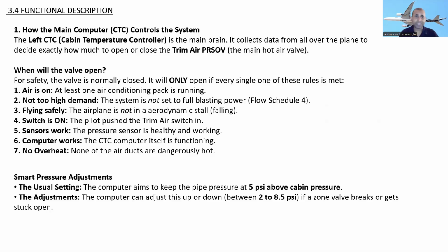Right. For safety, the valve is normally closed. The trim air regulating valves are normally closed for safety, because if it is open, very high temperature will come to the cabin and cause a big problem, right? So for safety, it will only open if every single one of these rules is met, right?